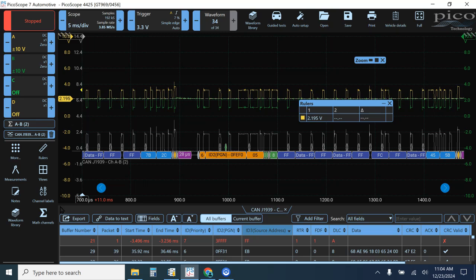It really is hard to troubleshoot. And in this case, we could use the fact that we knew it was the knock sensor. We had a clue that it was a knock sensor because I had a DTC that said the knock sensor was missing. So I'll change the resistance. I'll add it back in, but we'll put it to where it's not so much, and we'll see what the waveform looks like. We'll just add a couple of ohms of resistance.